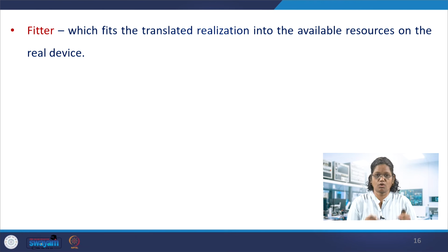So always your code should be in such a way that your design fits in the chosen FPGA. If the content doesn't fit, or if your program needs more resources, like the number of multipliers and logic elements being more, then it will immediately say the design doesn't fit into the device. So we have to reprogram it if the device is fixed. If you are not going for a larger FPGA, then for the fixed FPGA device, you need to make a change in the design.